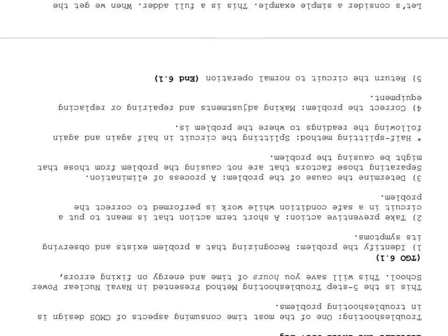Also, you want to shut down to a certain point. So you're still having the reactor run, but you have to be able to take out the specific circuit board, replace it with a backup circuit board, then take that old circuit board and troubleshoot it. You want to find out what the exact problem is, so that if you can find out the problem, you can perform another corrective action instead of just screwing up boards.